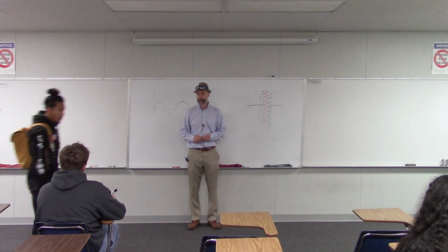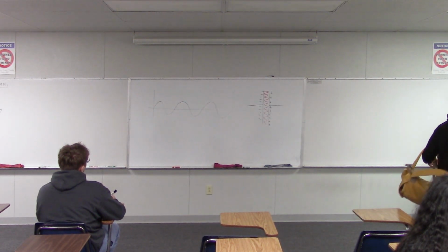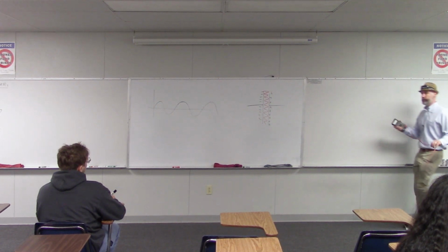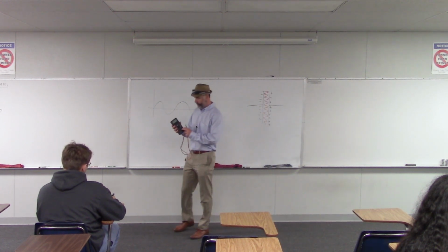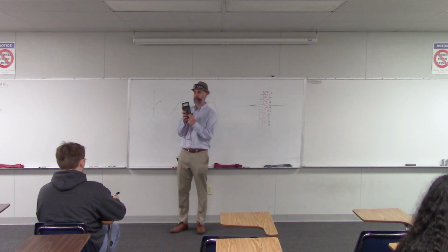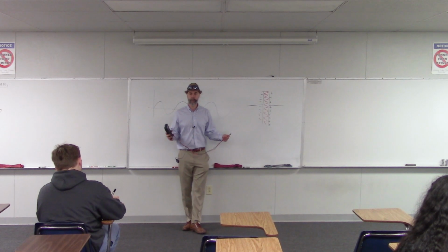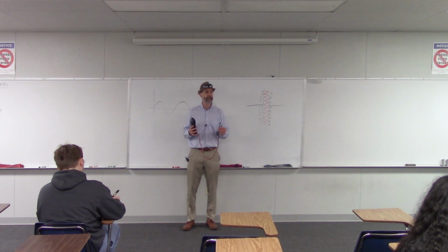So when we used the meter to measure capacitance, did we use these leads and hook up the leads to the capacitor? No. Instead, we plugged the capacitor into these two little holes that are right above the leads. And why did we do that? What was wrong with using the leads for measuring capacitance? Yeah? The leads have a slight amount of capacitance. Exactly.